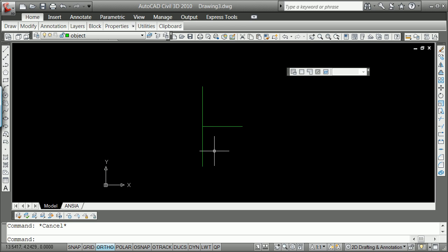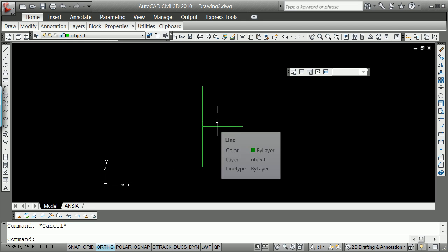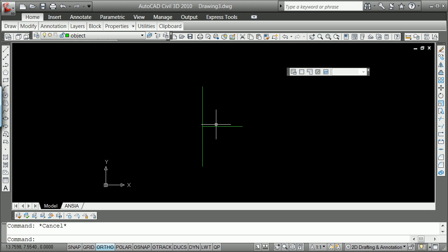Later on you see this actually, in this sketch, this line goes through, and then this line is actually attached by a gusset plate and it doesn't actually touch. That said, we also then potentially have a left click, spacebar, C, and we're going to rotate it 60 degrees. And this here, if you look at the 1-to-1, that should tell you it's 45, spacebar C, minus 45. You now have the structure drafted.